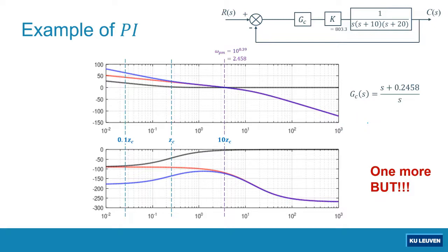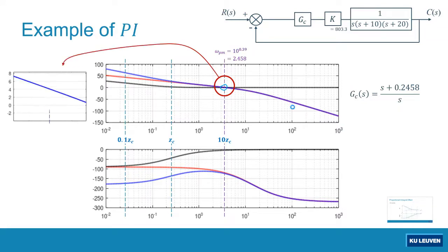Sometimes you might have a slight glitch when you check the phase margin frequency, and then when you look at the magnitude at the phase margin frequency, apparently it's not equal to 0 dB anymore. It will be slightly deviating from the 0 dB line.